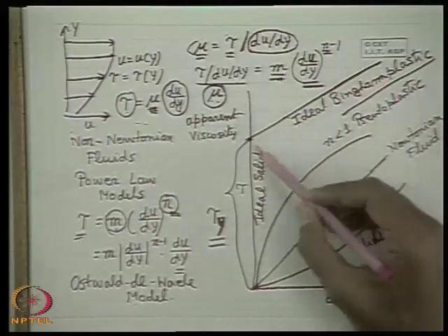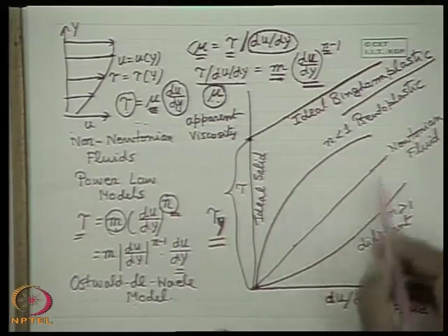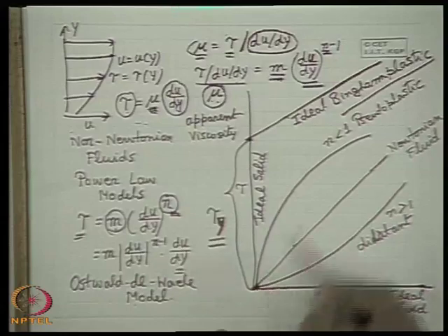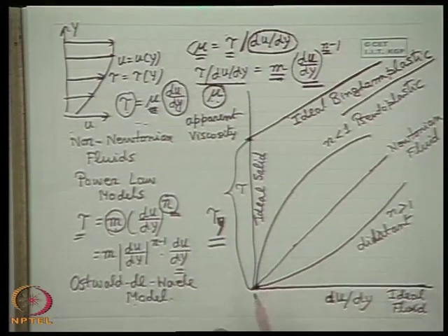But there is a little reservation in calling this class of substances a fluid. This is because they don't start from the origin. You know that the physical significance of any curve, either linear or non-linear, starting from the origin is that under an infinitesimally small shear stress, the fluid starts flowing. That means fluid cannot resist even an infinitesimally small shear stress under static condition. That means if you apply a very small, non-zero shear stress, the liquid starts flowing.